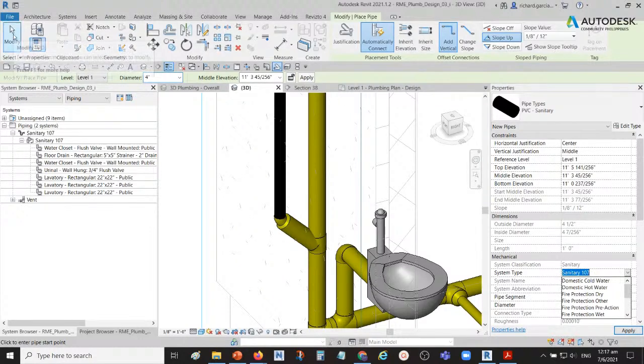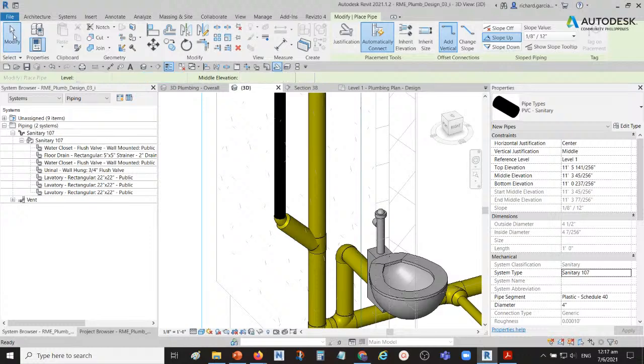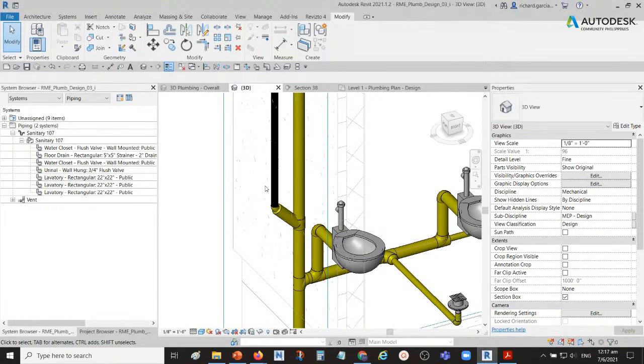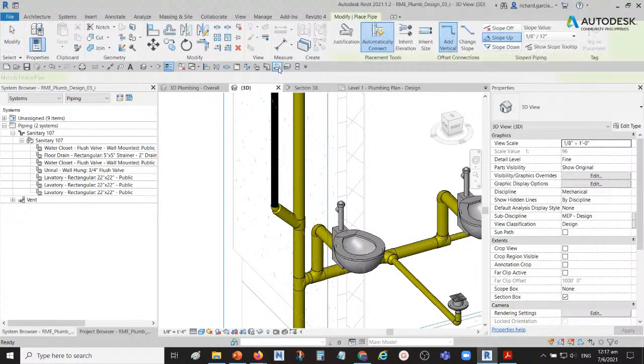Okay, because there are some settings wherein if your system type is wrong, the fittings that you would like on that particular layout are different from the ones that you would like to create. So that's why it's really important for us, especially for beginners, to use the correct pipe type before you lay out your piping. Okay, just click the pipe there.